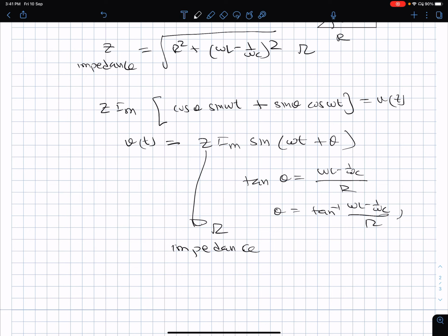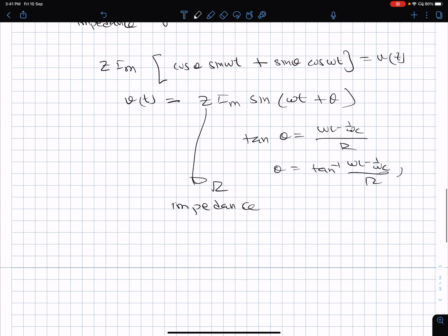Reactance will not, because it's only related to a storage element, either inductance or capacitance, that is storage of energy in magnetic field or electric field. Impedance, being a combination of R, L and C in general, will mean that it can also partly dissipate and partly represent a storage element, because it's a combination of R, L and C.